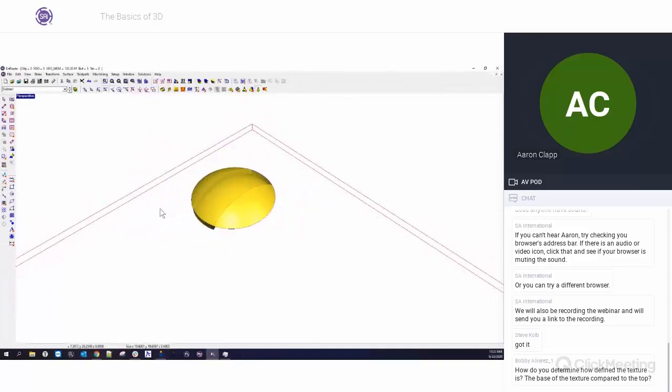This is really good again for if you wanted to do text and you wanted to insert it inside of the dome so that it followed the contour of the dome. That would be a really great way to do it. Just do a subtract with maybe like a beveled relief or something like that, and it would create that nice effect following the contour of the dome.